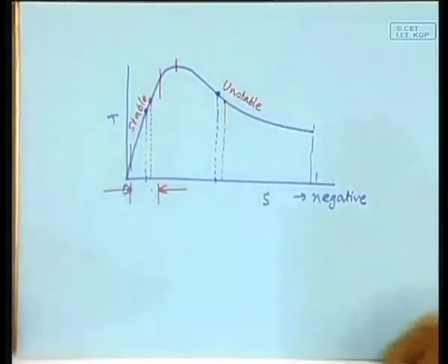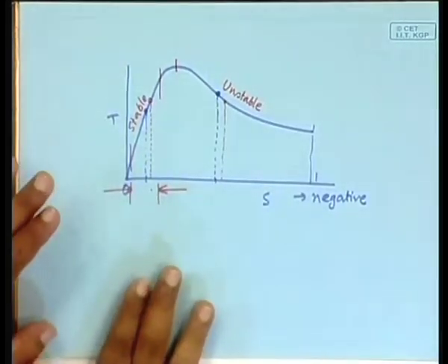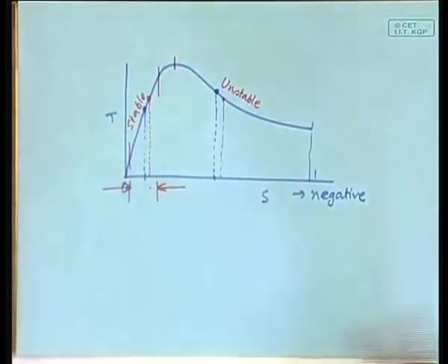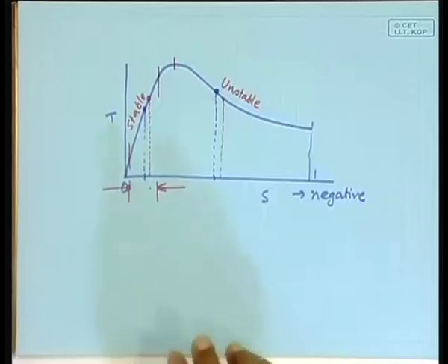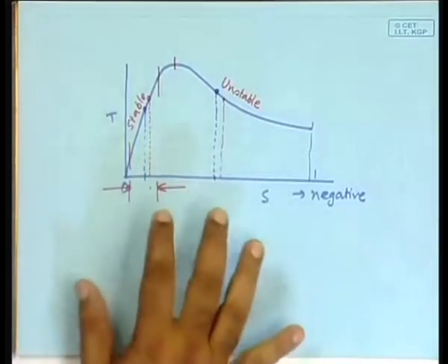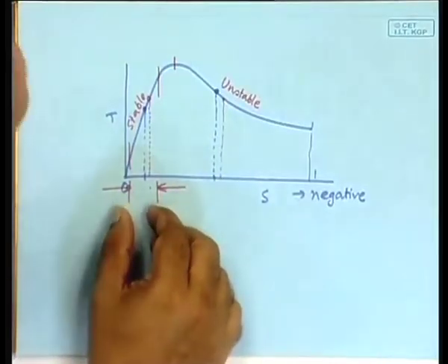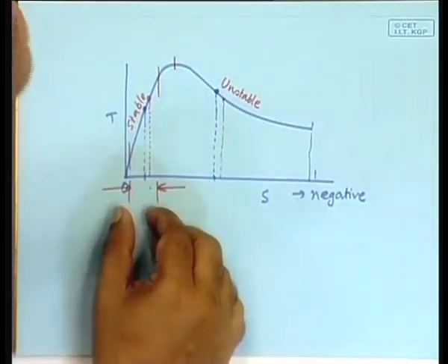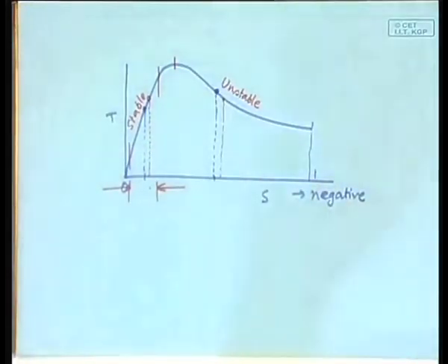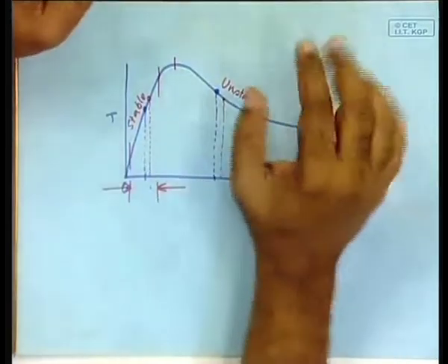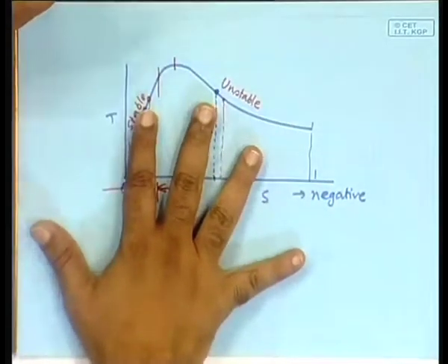So, I started by saying that the induction machine offers the advantage that it can operate at varying speeds, even though the frequency will remain constant, but it is not really so. Can you begin to understand that? It is not really so, because you effectively have a very narrow range in which you can vary the speed. Beyond that, it will become unstable. But still, there are ways to overcome this. I will come to that.